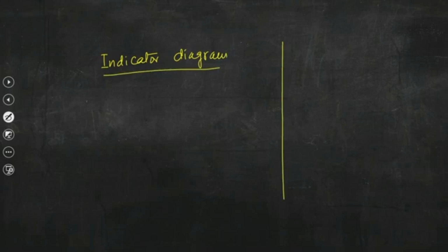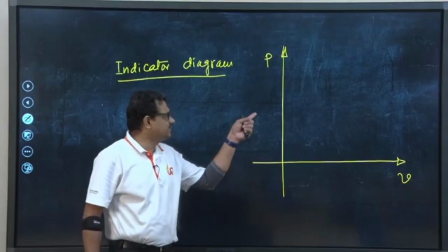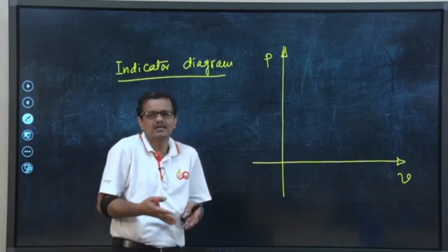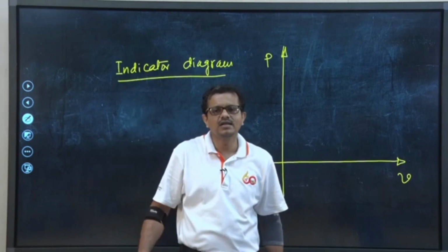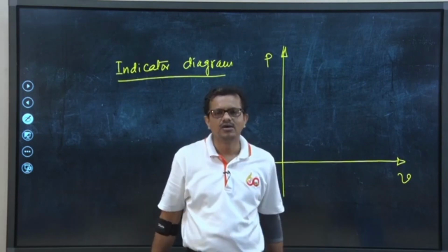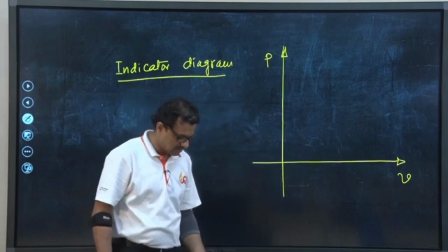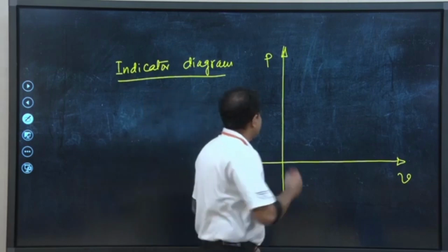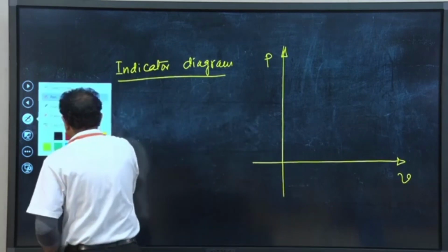As we have mentioned, we need to see the change in pressure with a change in volume, so we need to map the processes in the PV plane. What are the processes? Basically you know that they are intake, compression, expansion, power and exhaust. All these processes complete one cycle of a 4 stroke engine, be it an SI engine or a CI engine.